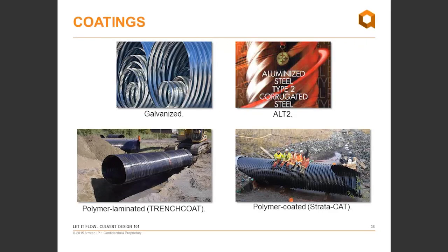Culvert slopes compared to ditch slope. Doesn't increased culvert slope allow for cleaning of the culvert? Well, yes. If you increase culvert slope and you have sediment in the natural watercourse, then you could still end up with sediment at the outlet end. I think that's what the person was asking about. But yeah, you could increase velocity by increasing the slope, but it's often not recommended because of what happens at the outlet end. That's great. Thanks, Patrick.